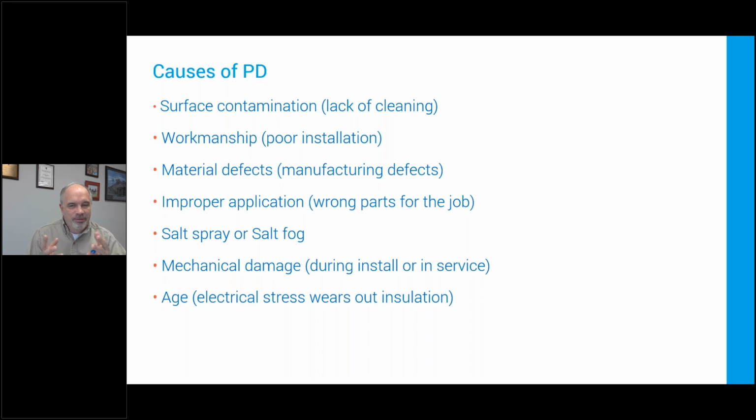Mechanical damage. Very often you'll see something damaged when it's installed, from the pulling technique of the cable, or we see it very often in buried cables in wind farms, where they're not buried in sand or a nice media, they're buried in whatever dirt was there, and rocks cause pressure on the cable and pinch the insulation. That happens. And then things do get old. Electrical stress does cause physical changes to the insulation, and over time it can cause paper oil cables to dry out, it can cause insulation to break down, and it does wear out. It takes a long time, but in a high stress location, it could happen faster than in other locations.